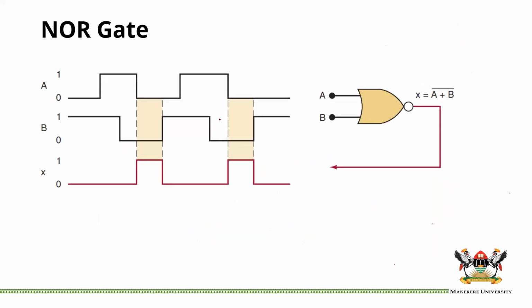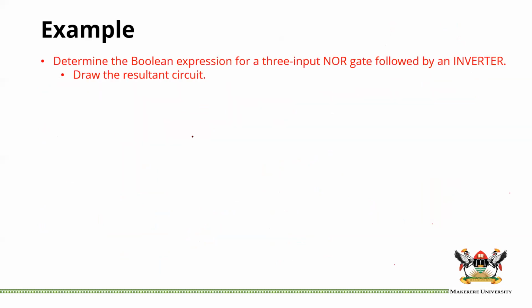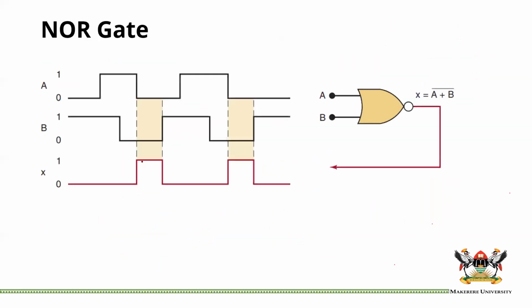So we'll just continue. Now, if you look at the NOR gate, by the way, this can be confusing. You need to probably do a small truth table every time you deal with these until you are very sure that you remember them. So the output should be 1, 1, 1, and 0.